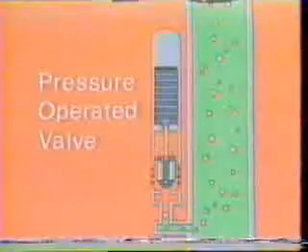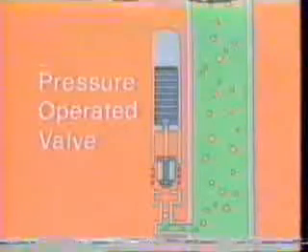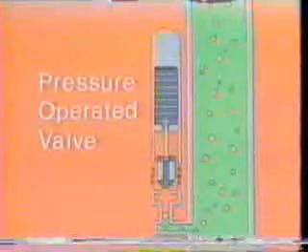Here we have a casing pressure operated valve. It is a single element valve for which we would like to calculate the opening and closing pressures. To do this, we must write a force balance equation for the valve.